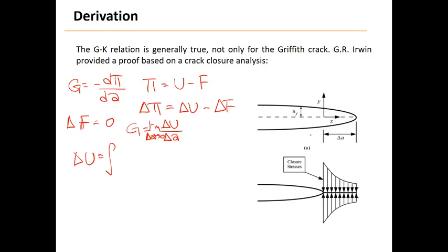The only thing that has changed between these two configurations is that the crack has extended. Previously we had stresses in front of the crack, and now, since it has extended, this region is no longer taking the stresses that it should be taking.